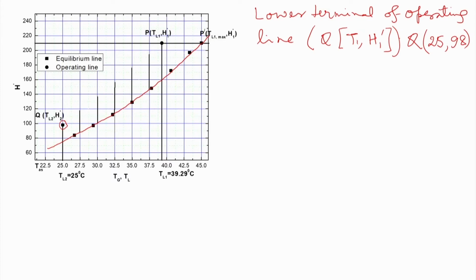Okay. Then the enthalpy of the feed air at the bottom point, that is P, we do not know where the actual P is, but that enthalpy value we know, because the moist cold air leaving from this dehumidification chamber has its temperature fixed as the wet bulb temperature or adiabatic saturation temperature of 30 degree Celsius.